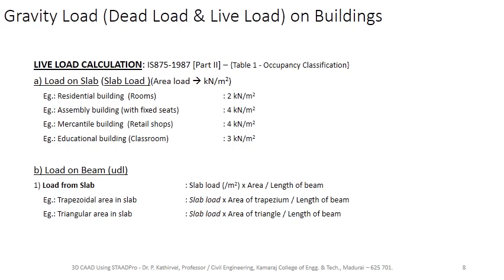This area load on the slabs are converted into uniformly distributed load on beams by multiplying the slab load with the area contribution of the load in the slab. Thus, the area load on the slab is converted into distributed triangular or trapezoidal loads on the beam.